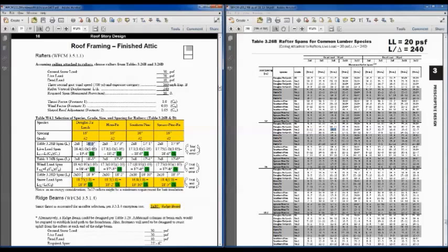So now for the live load application, we can take that 18.4 foot span and, if we had a thrust load, we could apply that, but we're just going to apply the sloped roof adjustment factor to it, and we see that it'll span 19 foot 4. So that works, greater than 16 feet. The 2x6 wouldn't work because that was only a 14-foot span, and this adjustment wouldn't have gotten us to where we needed to be.